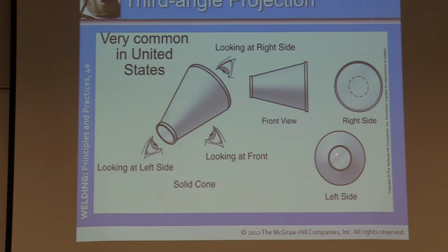If we're looking left side, we see this piece first, it's hidden, or a solid object line, so is the outside. But if you notice on this, it doesn't say that it's a hollow piece. What this shows me is that this is hidden, so this is telling me that it must be a solid piece because it's showing a hidden line. So right there was a good way to just understand from this one drawing. It tells me it's a solid piece, or that the right-hand side is solid at least.